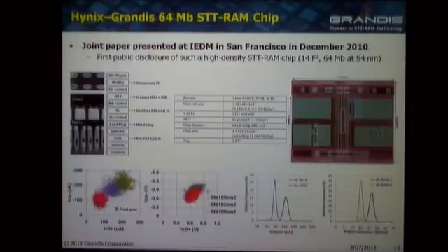So the net result of this is, if you just look at this resistance distribution from the chip on the right here, the green is the low resistance state, the red is the high resistance state. You can see not all of them are switching. It's about a 95% switching yield. So that's where we were in December. But I think within the next few months, hopefully in the second quarter, when we put the dual MTJ devices in this chip, this should go very high, above 99.9%. So I hope we can get fully functional chips from this process very, very soon. Here you can see a few devices shorted. So there's about 1% of those at the moment.